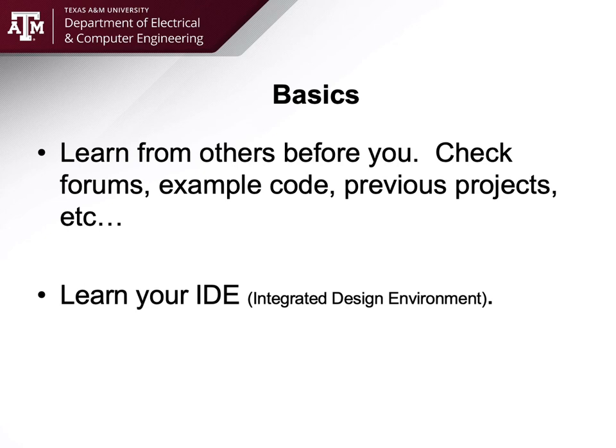Also, learn your IDE, your integrated development environment. If you're going to be using, for instance, Microchip PICs, and you're going to use MPLAB X, please download MPLAB X early and learn it. Don't start learning the tools basically the day that you need your tools. When you actually start writing the real code for your project, you want to have already done Hello World and the basics.